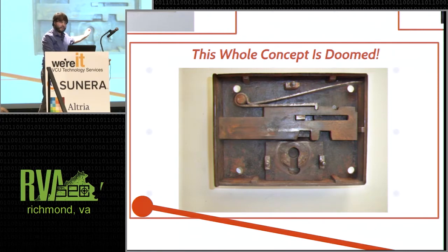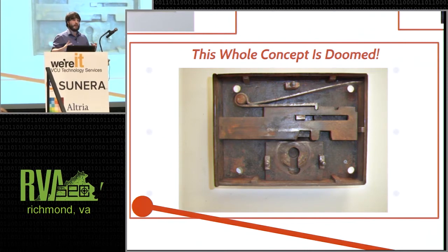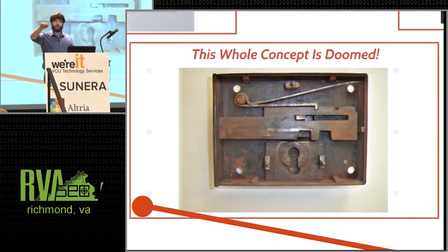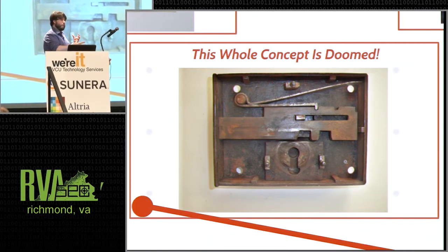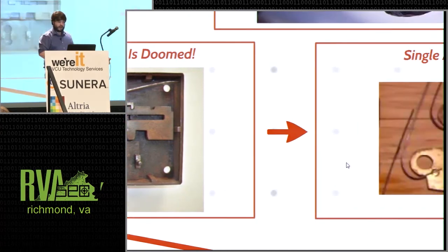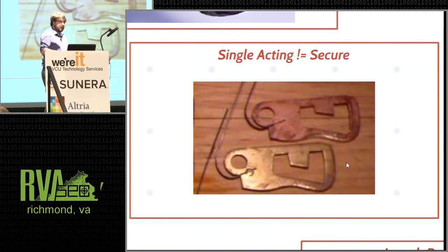The basic idea is that by lifting this lever, you are freeing this notch so that it can slide out. So you lift the lever, the key operates on the bolt, sliding it out. The little protrusion drops back down into the next notch, and it's locked again. And that's dead simple, but his idea was, if I add this active element, it's going to be very difficult for somebody to get an impression of the lock. Now, this would often still be paired with a box of wards, but it would also be lifting this active element.